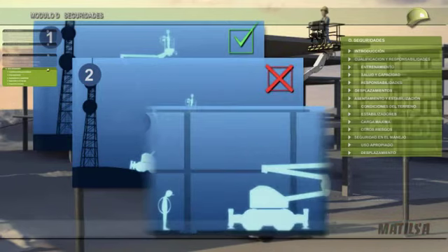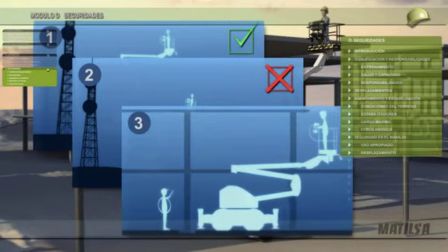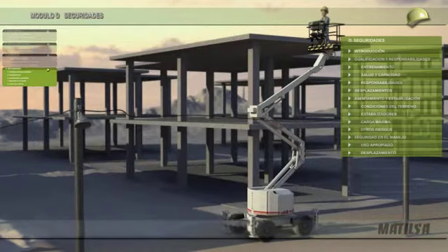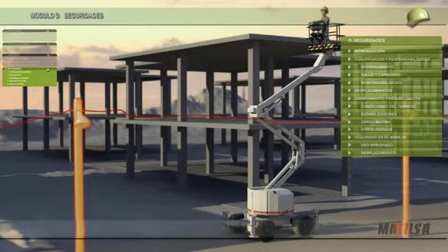When you do transfer material while up on the machine, it would be advisable to have somebody at ground level who can indicate the existence of any obstacles that cannot be seen from on the platform. Before doing the transporting, we will make sure to check that the stabilizers are neither out nor extended, that the harness is properly tied up, that care is taken with any cables or ropes which are being used.